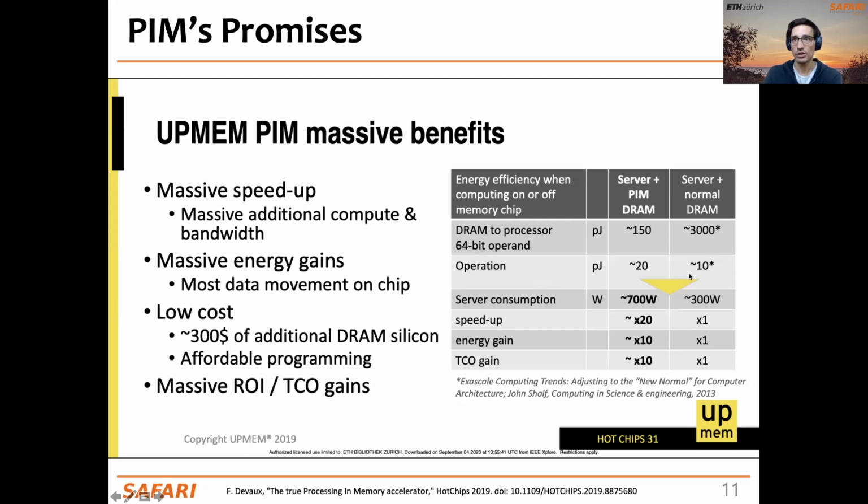Observe the difference between these two numbers, and remember the slide that we saw in the previous lecture, that motivational slide from Bill Dally, where we compared the energy of accessing data in memory with the energy consumption of the execution of computation in the cores. And we saw that there were essentially 2-3 orders of magnitude difference.